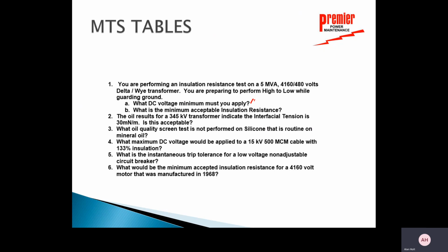Well, in the maintenance standard, table 100.5 is one that we want to look at quite often. And if I look at that for a 4160 volt transformer, then the minimum voltage that I would apply would be 2500 volts.